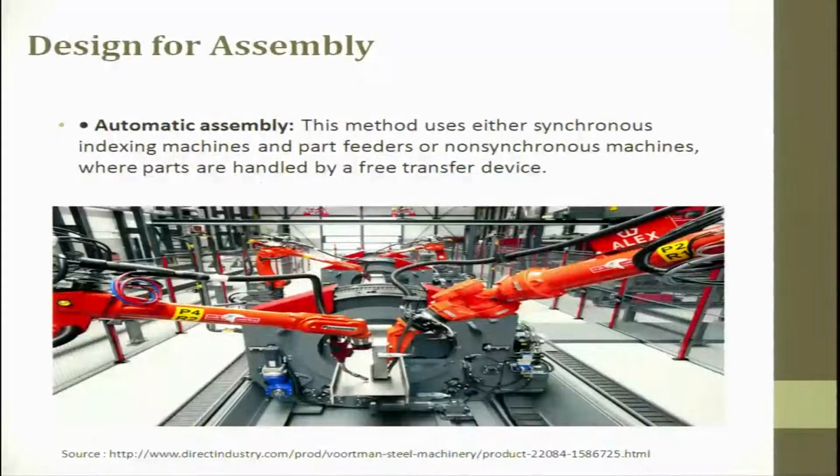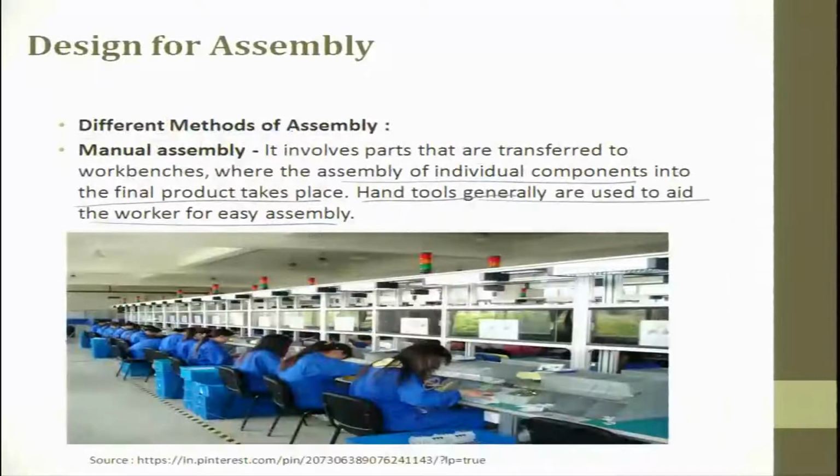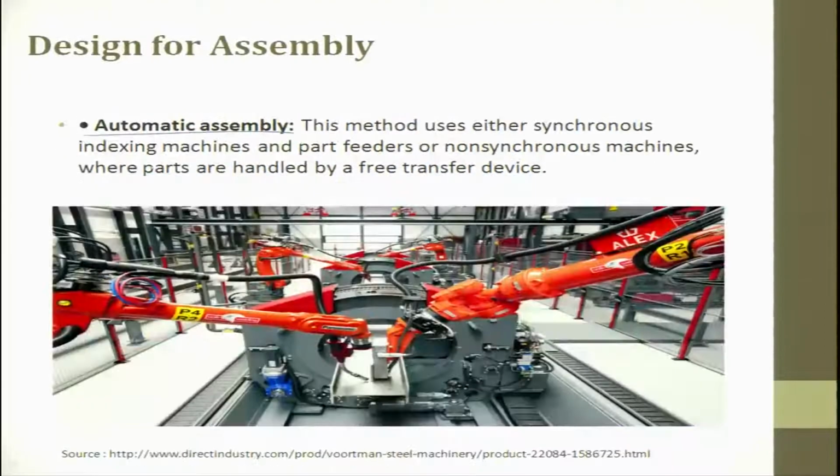The other way around, I do not want to have man. Why do I not want to have man? One, there is a possibility that defects can happen because of fatigue, and second, sometimes because of wrong judgment they could have done an assembly. And then the forces they apply in fixing can vary from human to human. So, these are some of the possibilities for error to happen when you do assembly in the manual way. In order to avoid this, we try to use automatic assembly.